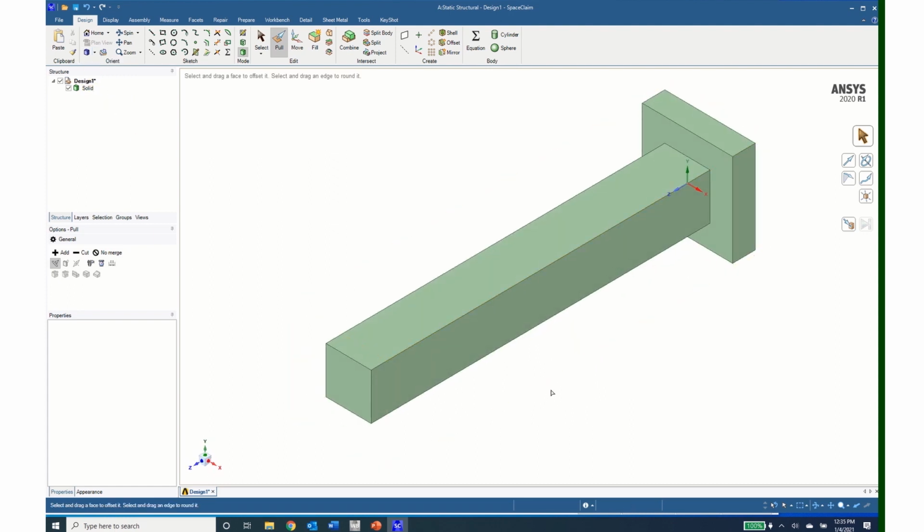Now I'm ready to compute the fillet radius. To do that, again, I use the Pull tool, so I'll click on Pull. Then I come to this line, and I make sure I click on the line, and I simply pull this out, and I type in 4, enter, and that gives me my 4 mm radius. I then come to this line, pull on it, type 4, enter.